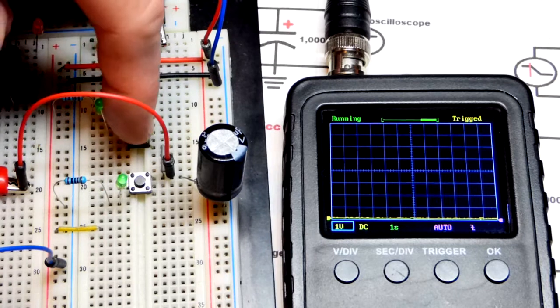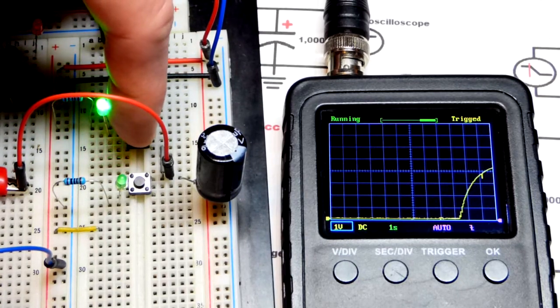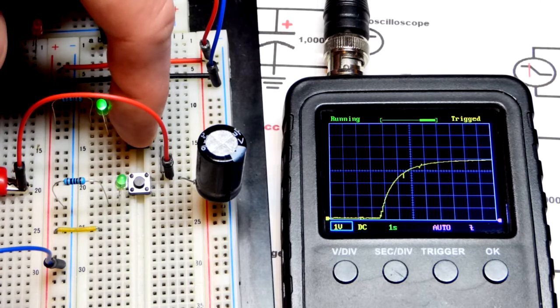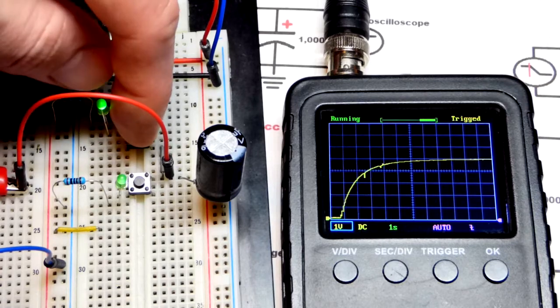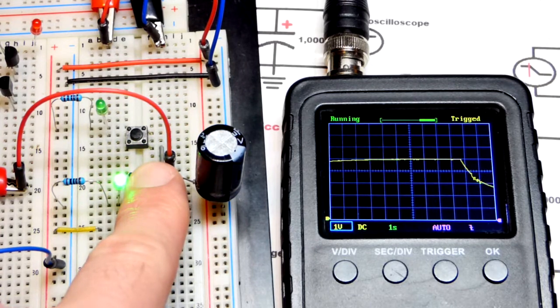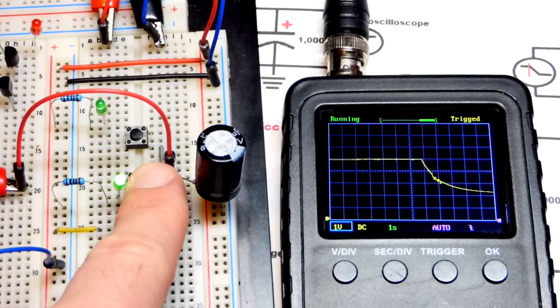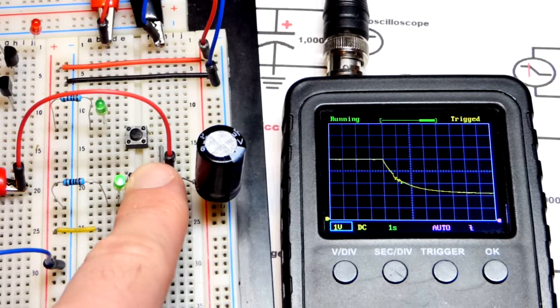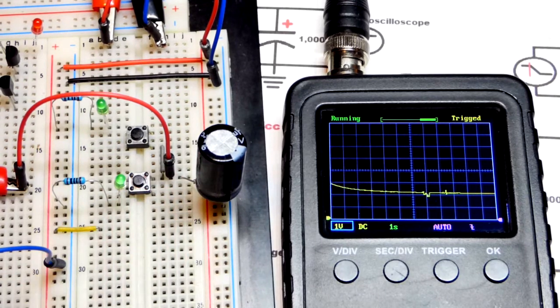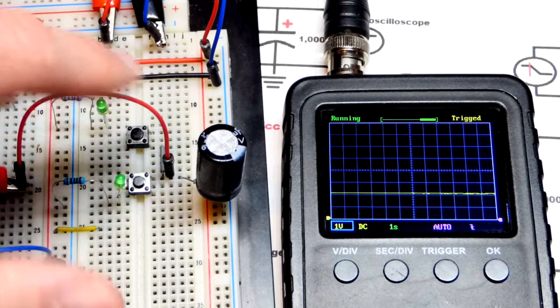But in any case, now we're going to look at the curve going through an LED. It's still a 7 volt power supply right there. And there you can see we're up 1, 2, 3, 4, about 5. So with very little current going, it's blocking about 2 volts. And then when we discharge it, we're going to fall eventually to only about 2 volts above the 0 volt down there. So we got some noise there. My finger's kind of touching it, but in any case, there you can see that we're 2 volts off the rail. That's because the diodes take a couple volts before they will conduct, and then they block that voltage from everything else.